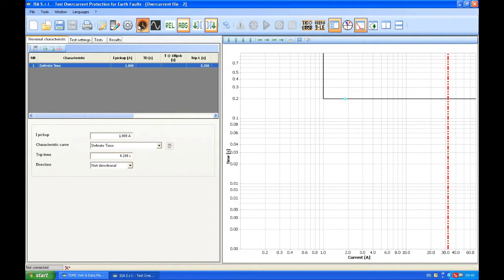Moving on, these 2 buttons define whether we are perceiving measurement of time in seconds, which is this one, or in hertz, as here, meaning in cycles. So since I defined my cycle as 50 hertz, 200 milliseconds is 10 cycles.